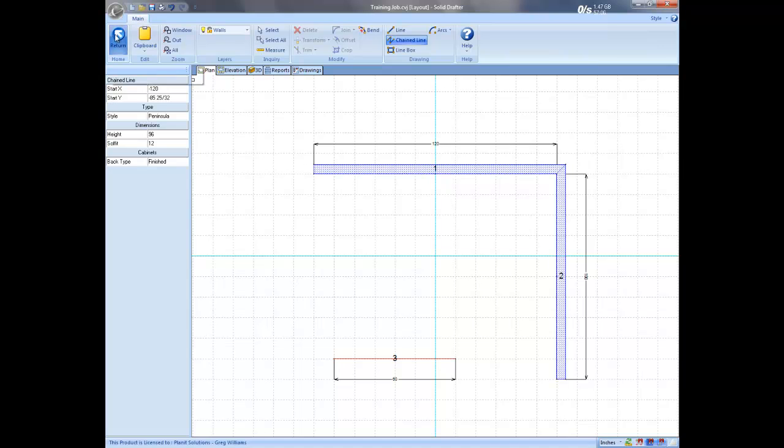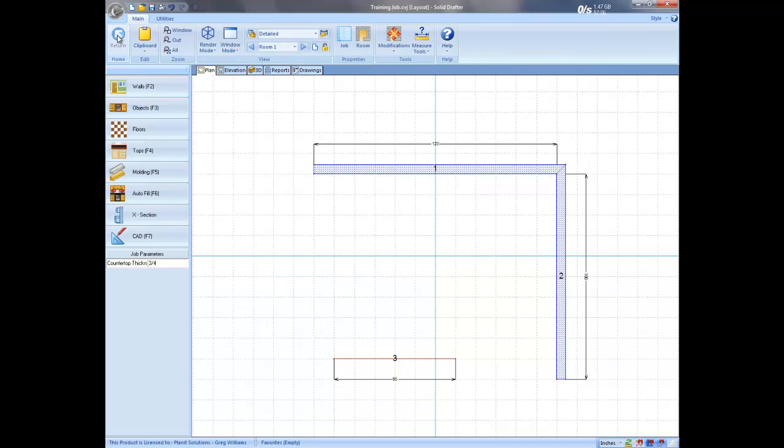If you don't want to show a cabinet attached to a wall or installed on a wall, such as an island cabinet or a freestanding bar, you can draw a peninsula wall wherever you would like in the design, and cabinets will also attach to that wall without showing a wall in the design in any of the views. The main point to remember is to draw in a clockwise motion around the center of the workspace.